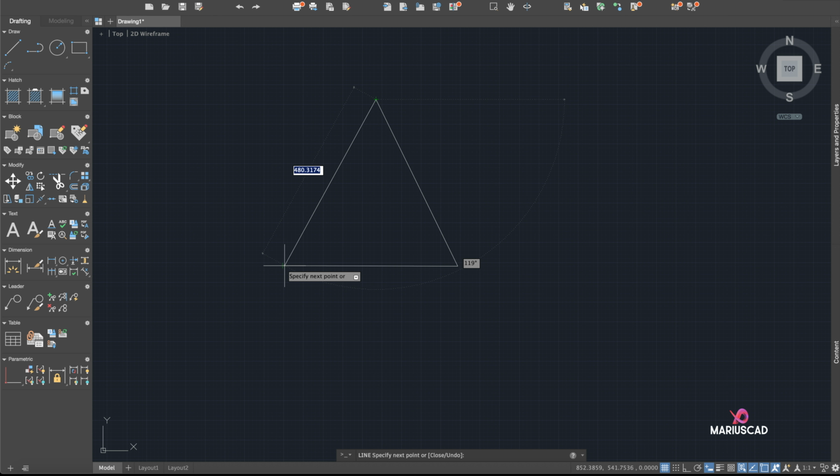And the fourth one exactly in this point. You can see here a little green square. Click here and enter, because when you click enter, the drawing is done or it's finished. If you are not clicking enter, you can still continue to draw. For example, here, here, and you don't want it. And now delete it.